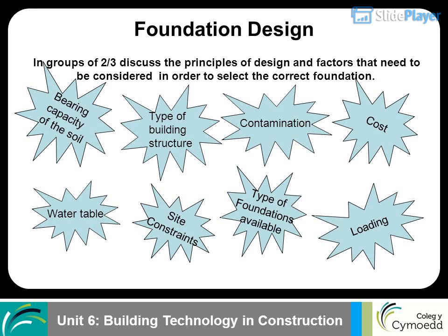Foundation design. In groups of two or three, discuss the principles of design and factors that need to be considered in order to select the correct foundation. Bearing capacity of the soil. Type of building structure. Contamination. Cost. Type of foundations available. Water table. Loading. Site constraints.